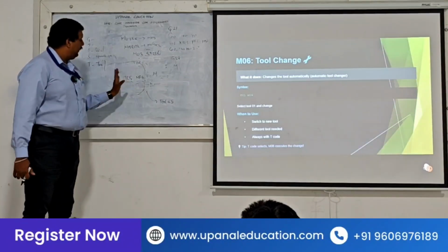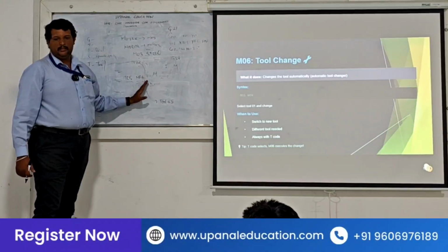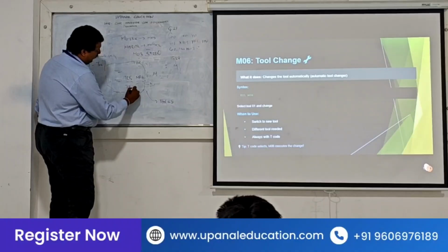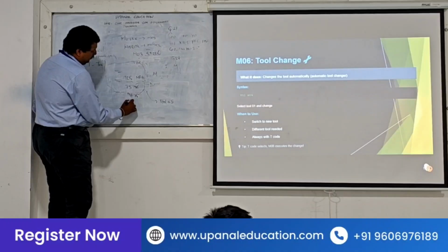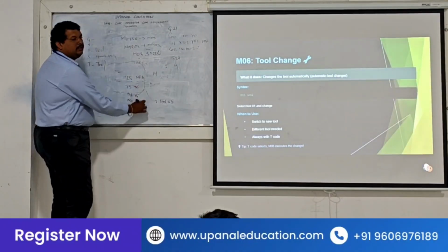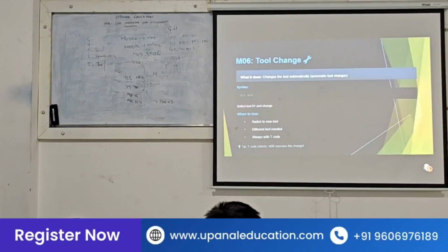This can be anywhere. We can even write M06 T5, or T5 M6, or M6 T5, or M06 T05. All these are the same, provided we give it in capital letters.